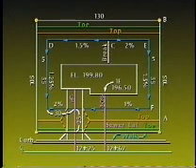change in elevation. From the site plan, we know that the dimension from the back of walk to flow line is 25 feet, and that the top of the slope is 5 feet from the flow line, and the toe of the slope is 1 foot from the back of the walk. This leaves 19 feet for slope. The grade is the difference in elevation between point A and the elevation of the southeast property corner, divided by the distance allowed for slope on the site plan.